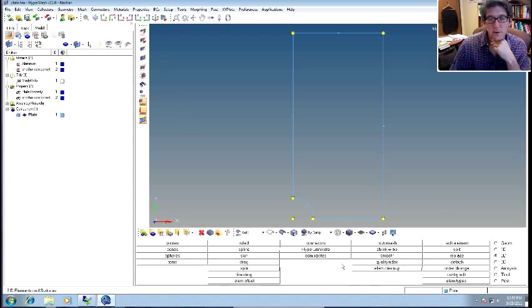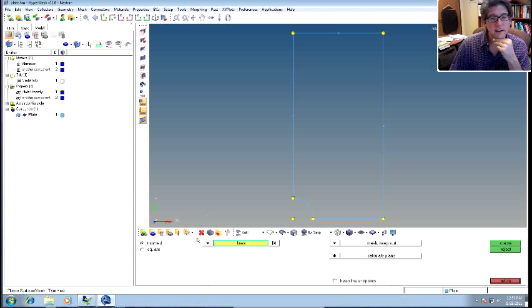There's lots of different ways of doing this stuff. If you have a surface, you can do auto mesh. You can do ruled surfaces, spline-bound surfaces. You can do a drag, where you take a line and drag it along a generator curve and make 2D elements. But we're just going to do planes. I use this a lot.